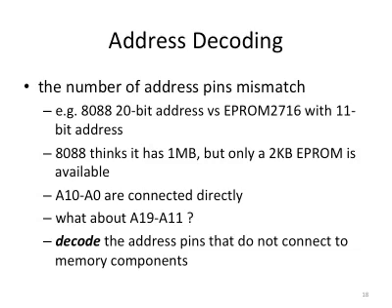Yeah. Are the stop and acknowledge on the same serial bus, or is it some kind of other line? It's on the same serial bus, it's just the one. It depends on the combination of the control signal and data signal. So they have some special signals treated as control, special control bits.